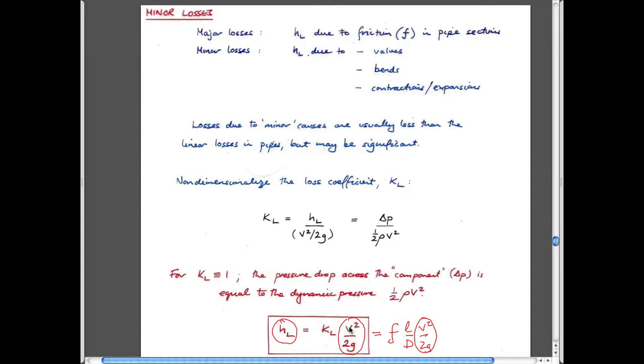And so it needs to be the velocity in the fitting, of course, as indeed this is the velocity in the pipe, not the velocity at the ends where it comes out in Bernoulli, so you need to correct for that. And you can rearrange this in different ways.